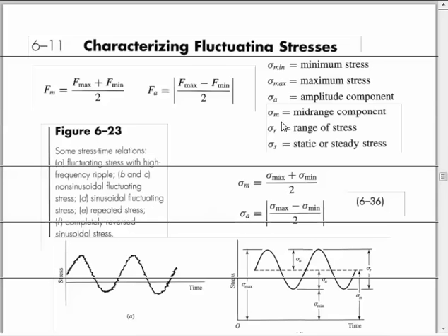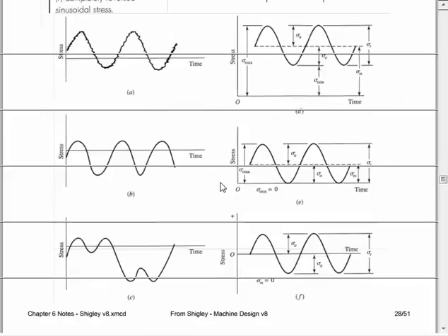Okay. We said that more often than not, the real kind of stress loading that we have over time is not the fully reversed, but it's a more general fluctuating kind of stress. Okay, here are some samples of fluctuating stress. Here, here, and they're not necessarily some sinusoid. We may have this combined with that over time. We could have any kind of loading that we can physically reproduce over time.